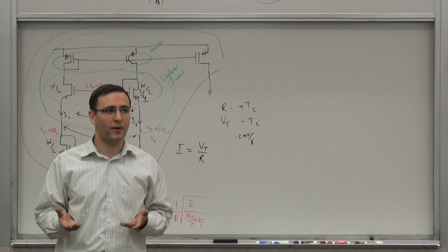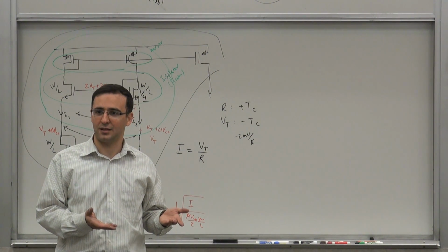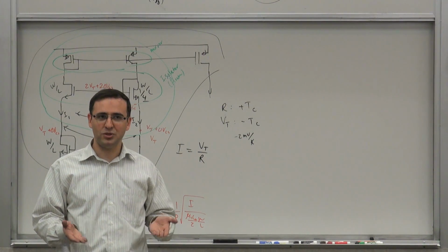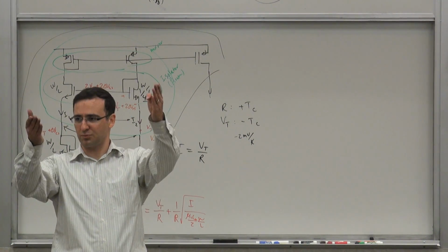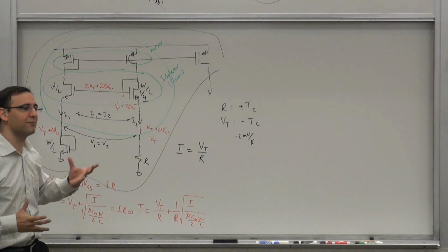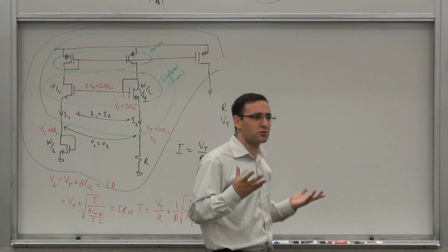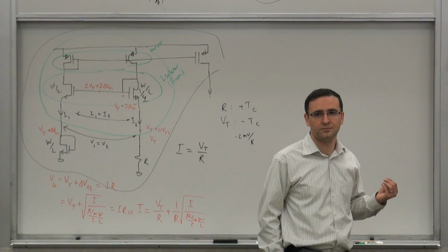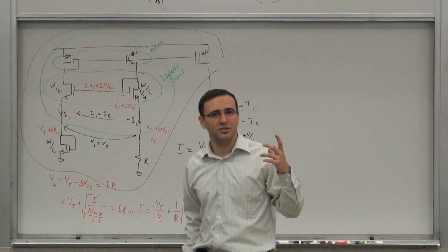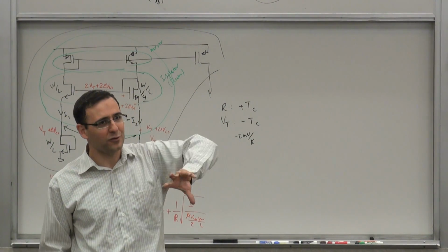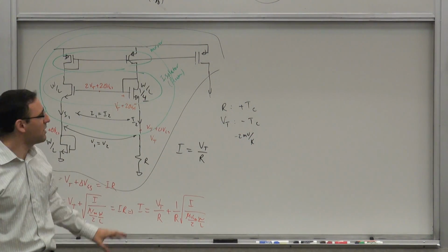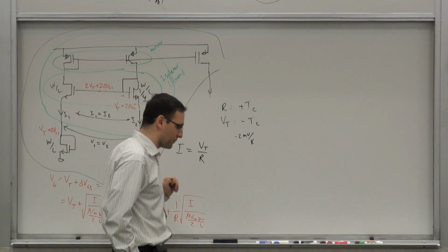If you have a ratio of a 5 kilo ohm to 1 kilo ohm resistor that's made out of something, it remains the same with temperature, because temperature increases both of them by the same percentage, so the ratio doesn't change. So you will see that eventually the things that are independent of most things are built on ratios of things. That's the trick. That's the ultimate trick. But to get there, you have to know how to make things that are defined only in terms of ratios.